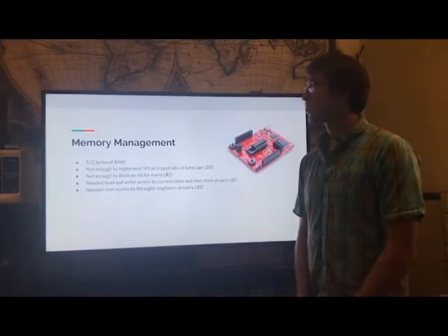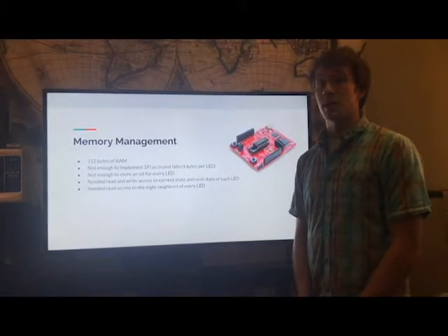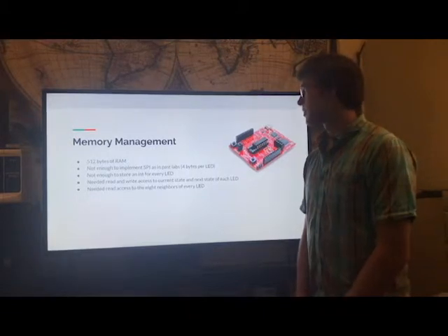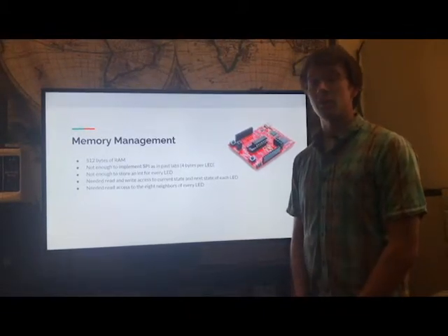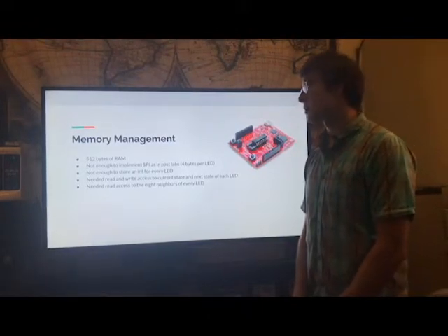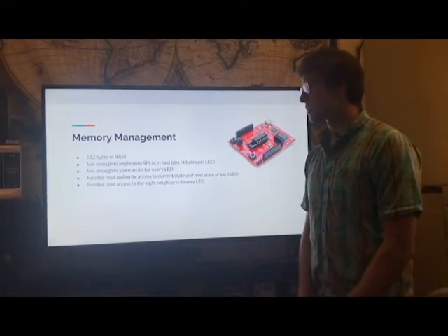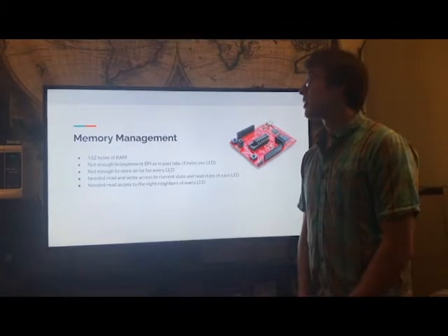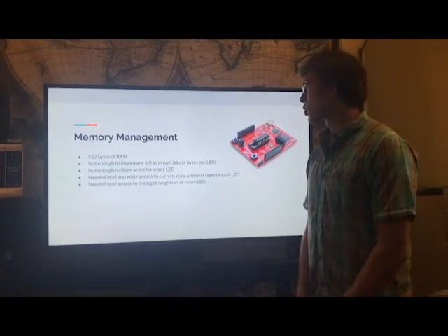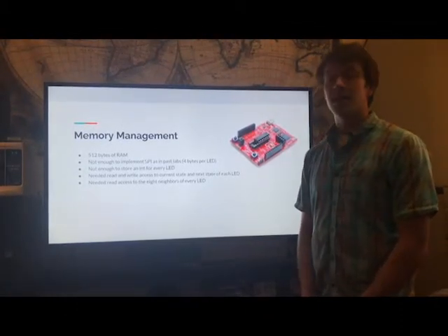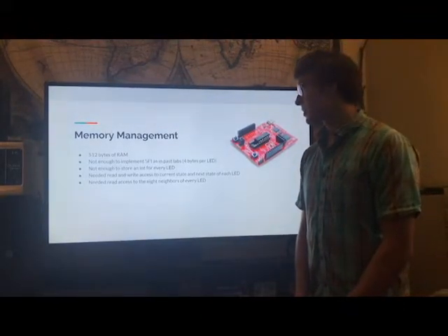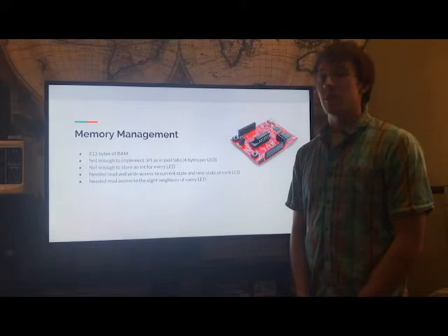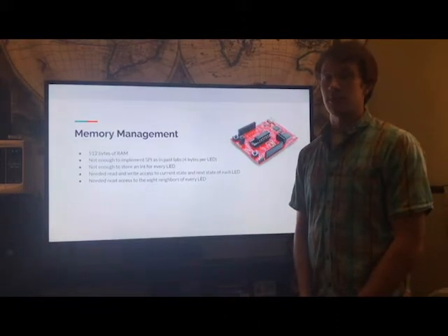The MSP430 only has 512 bytes of RAM, which is not enough to store 4 bytes per LED for the color and brightness as we've done in previous labs using SPI communication. It's not even enough to store a single int for every LED. So we needed to come up with a more clever way of storing the current state and next state of the LEDs in the simulation, as well as keeping track of the 8 neighbors of every LED in the simulation.